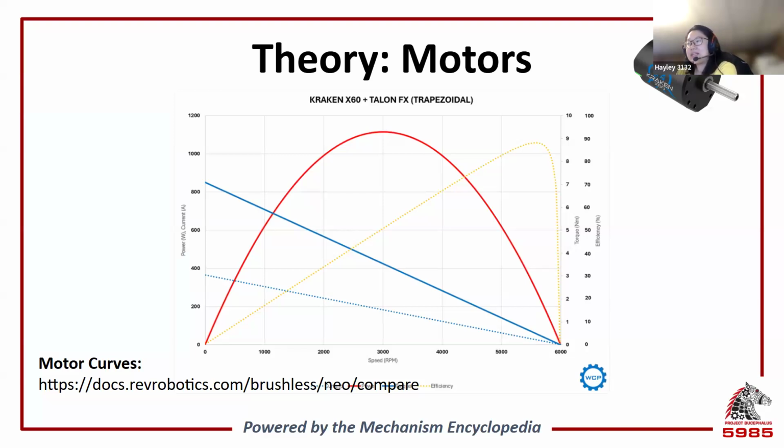Keep in mind that this is while the motor is being powered, which means the only reasons it shouldn't be spinning is if it were broken or stalled. The y-axis of this graph uses different units and values depending on the information that we're interested in. They use different colors or different types of lines, so make sure to reference the legend at the bottom of the graph and also read the axis labels to understand what units you're working with.